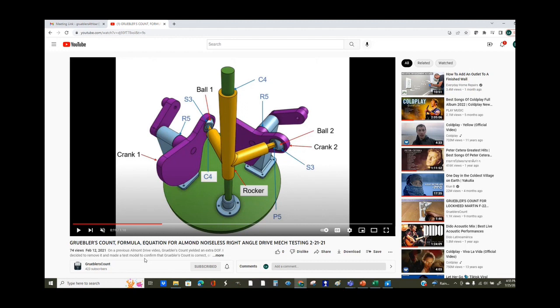You see that? One thing that's nice about Gruebler's is you don't have to worry about lining things up so perfectly. You can use bolt hole tolerances and it works fine. One of the things Brian and I worked on, we made Universal Studios' first animatronic hand. It was bigger than my hand. That's like a 6-foot figure. I was using Gruebler's on all the joints in there, and I didn't GD&T anything. I just used bolt hole tolerance, and it went together fine and worked great.